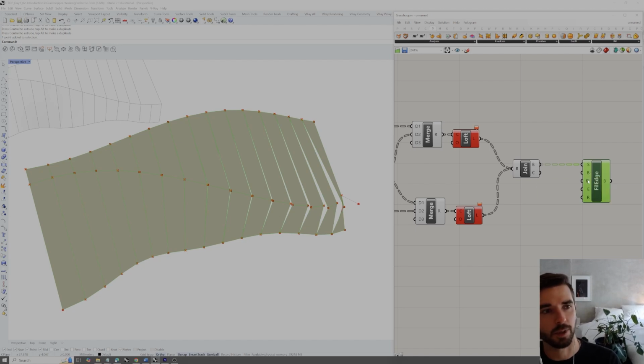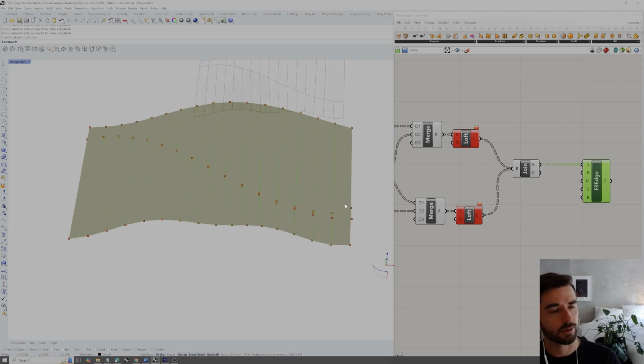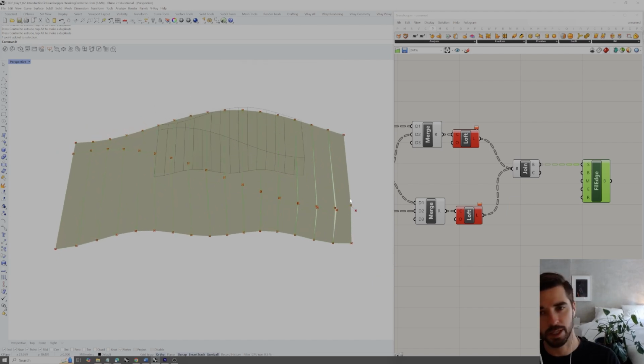Okay, so now we just need to go through the inputs for this fillet edge and see what it takes and how we can infill those. So metric rolling ball is totally fine. These are just ways that it's actually going to perform that fillet operation. Then we have edges. If we're thinking about the edges, and we know that these panels are basically just two panels joined together, and we have three edges defining them, our three lines that we made, so the bottom, middle, and top.